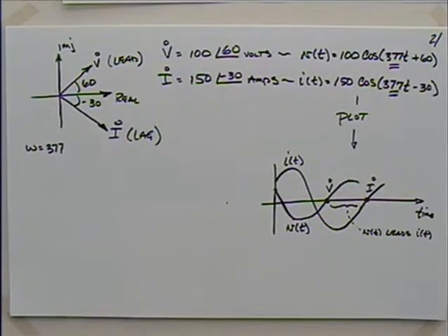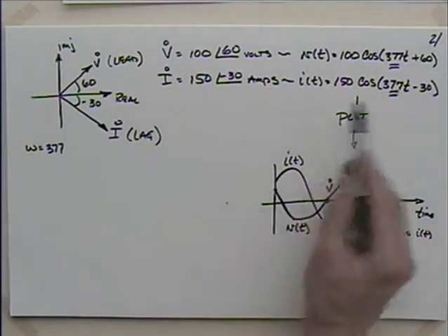Not necessarily, no. When you look at the oscilloscope, you can't tell which is voltage or current. In fact, neither one is current, because the oscilloscope is measuring voltage. We take one of the voltages and divide by resistance, and that's where we get the current. Okay, so those that have been struggling with leading and lagging,